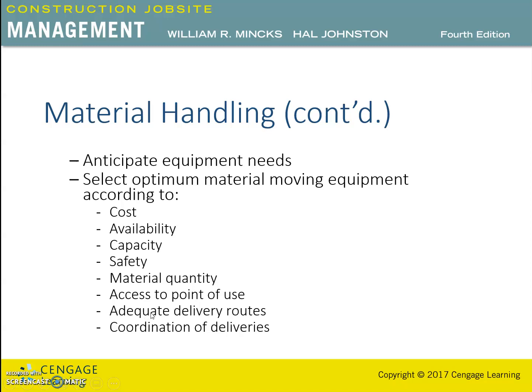Deliveries should be scheduled and coordinated, even though exact delivery times are not always available, particularly when the delivery is to be made from a long distance hauler or common carrier. Because the typical job site will receive many deliveries during the day, scheduling the time of the delivery will ensure that equipment and personnel are available to promptly unload the truck. So the contractor should prepare for the delivery by having available the appropriate amount and type of labor and equipment.